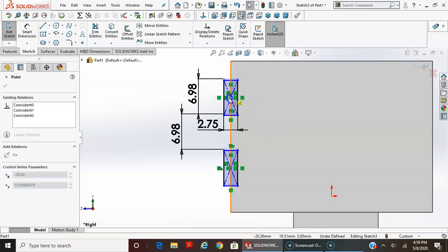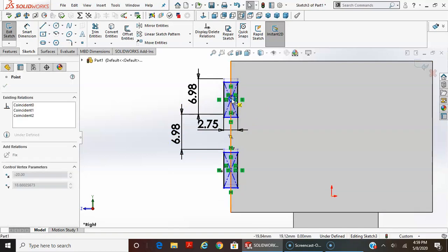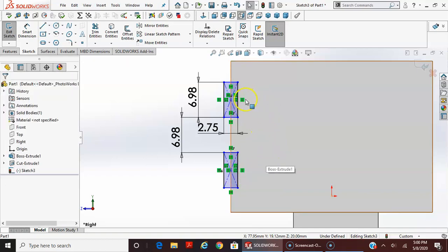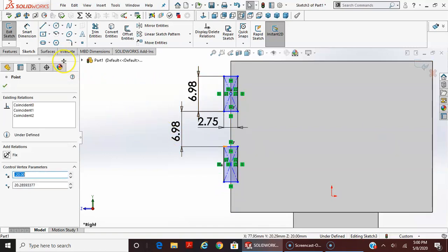So there is a dimension of the length of the slot, the depth of the slot, and the distance between the slots. However, there is no, in this case it would be a vertical dimension from this edge or from this edge. There's no vertical dimension of what that dimension is. So you could technically put these slots anywhere along this vertical edge. They're missing a dimension there.